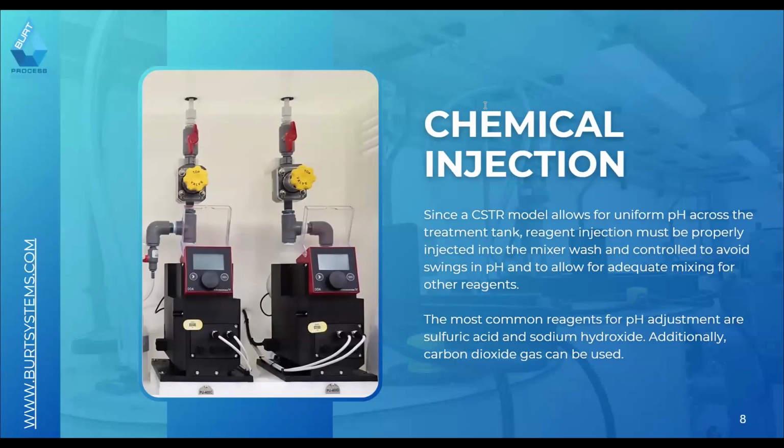There are other ones like CO2 gas that can be utilized, which you see a lot in beverage manufacturing or with different people that use a lot of aerosols. But regardless of the style that's utilized, they need to be 110% double contained. They need to be kept separated, and all the reagent plumbing, whether that's tubing or hard pipe design that goes from your reagent injection to your tank or your circulation lines, all double contained,